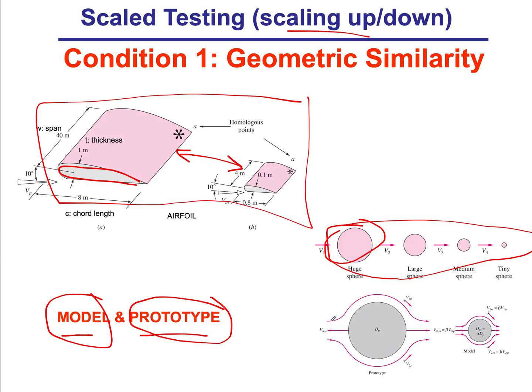And here you see an example that, because we're after the fluid dynamics forces, the flow pattern will look more and more the same if you have the same shape. So it makes sense. That's more of an intuitive argument. If you don't have geometric similarity, scaling up and scaling down your results will deviate more and more from the actual truth of the sought after result.